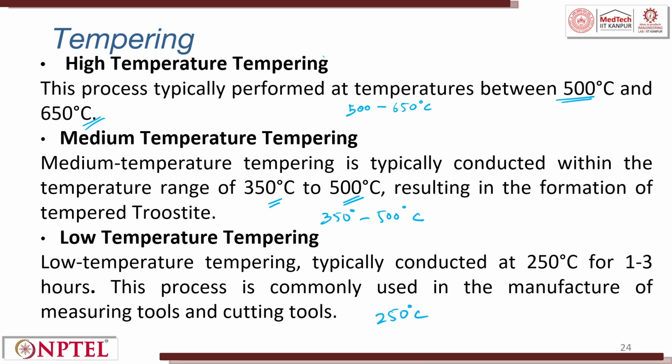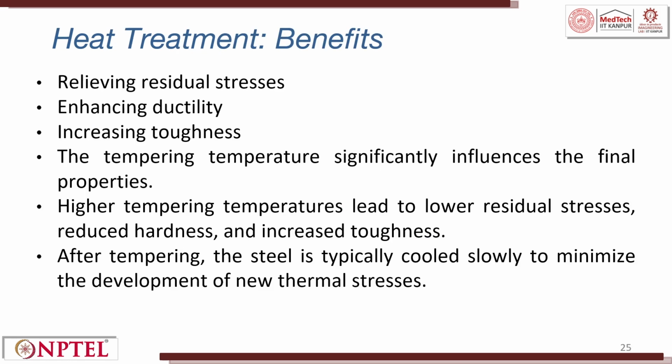The process is commonly used in the manufacturing of measuring tools and cutting tools. We do low temperature tempering so that we get a sustained stable microstructure. So the heat treatment benefits are relieving residual stress, enhancing ductility, and increasing toughness.